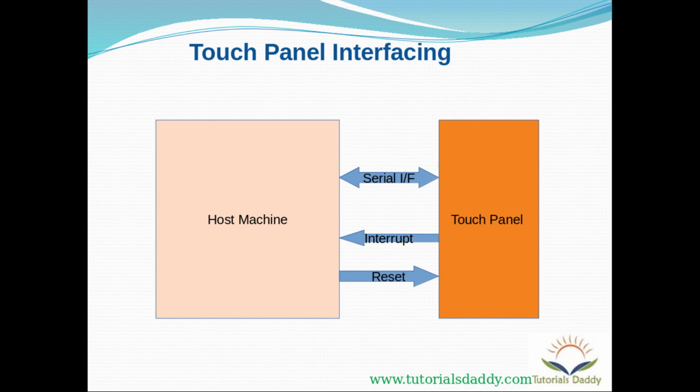Now let's say you are using your mobile phone and you are tapping on top of your screen and you are tapping on the bottom of your screen. Depending upon the menu icons, it will take an action. The area where you are tapping, the menu icon which lies there, that only will get notified and it will generate event accordingly. So it means we need to know exactly where the user has tapped on the screen and what is the x and y coordinate. So that x and y coordinate basically we need to read from the touch panel.